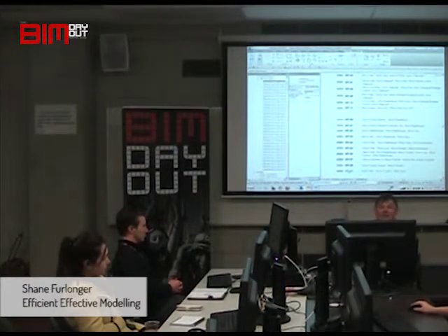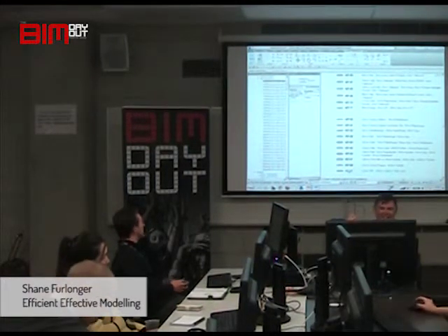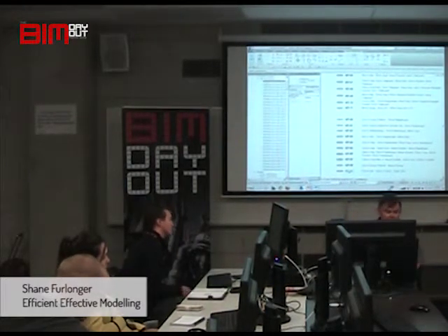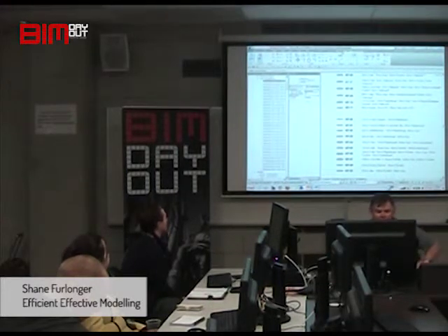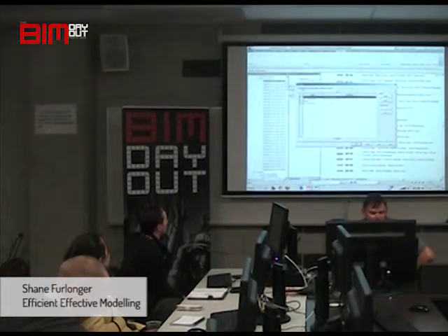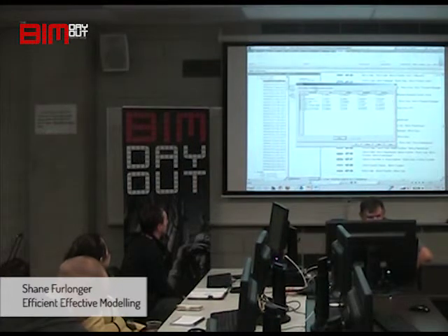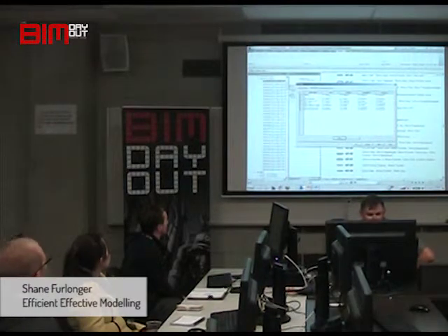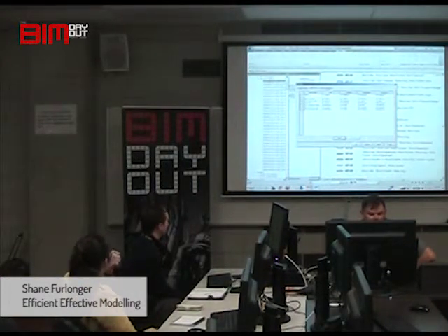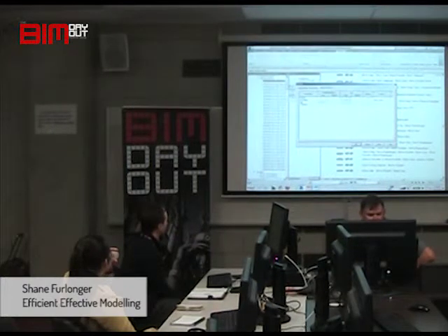I suggest that everybody gets their head around phasing. Phasing is good. A lot of people think, God, bloody phases, I can't understand them. And it is difficult because they've named things with the same name. You've got your project phases, and then you go looking at phase filters, and it says new, existing, demolished and temporary. Okay, that makes sense. And then you go looking at this, and again you've got existing, demolished, new and temporary. Okay, that will make sense as well, so you think.